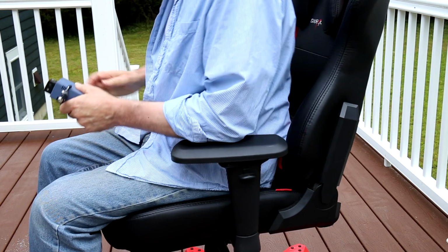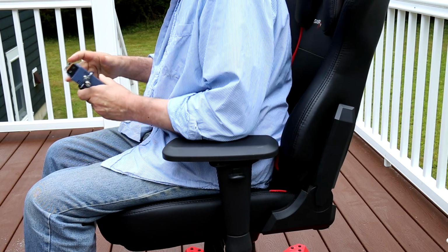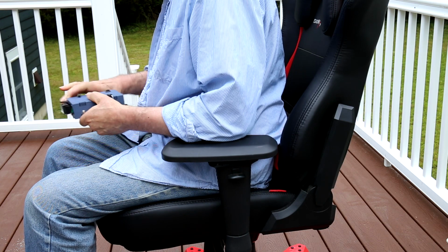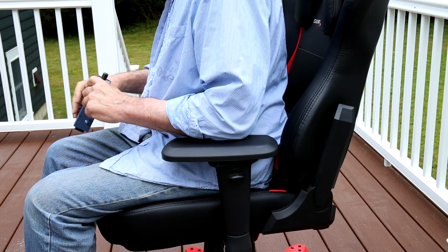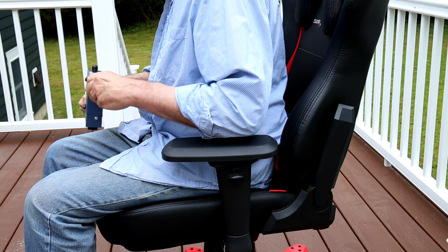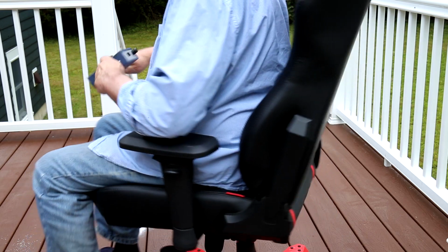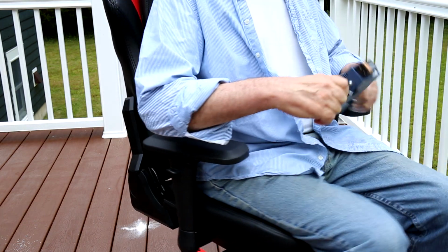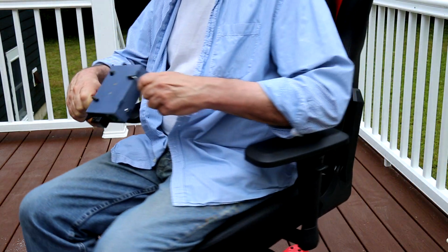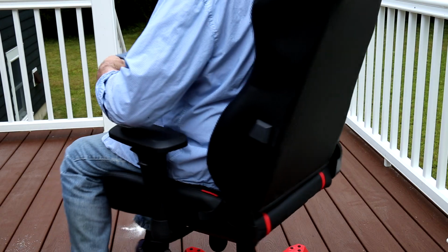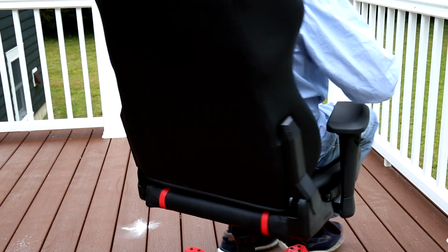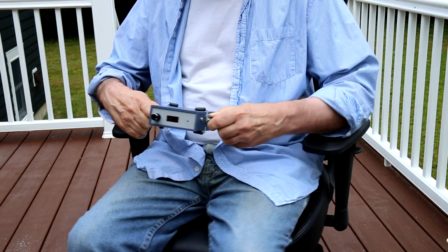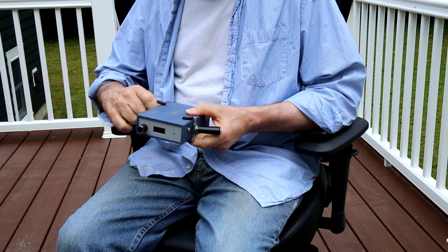The BNO055 measures elevation from gravitational effects. Those measurements should be calibrated, but nearby objects shouldn't have any effect on it. My biggest remaining challenge is magnetic calibration. The BNO055 measures azimuth magnetically, so it can be affected by nearby ferrous material, such as steel telescopes, binoculars, mounts, and tripods. In theory, these effects can be calibrated away, but I haven't yet worked out how.